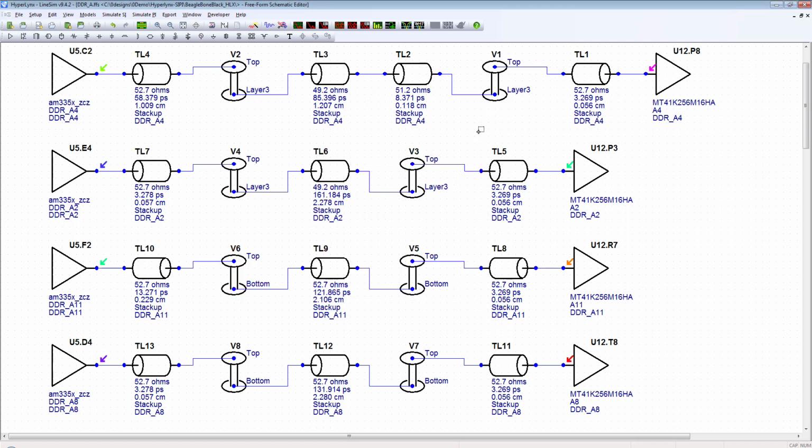So again, in previous statements, we said our expectation is, because of the very nicely matched address bus, we have only a picosecond of skew. Now let's do a simulation. I downloaded, as I said, IBIS simulation models for the Sitara processor as well as for the Micron DDR3 low power memories.